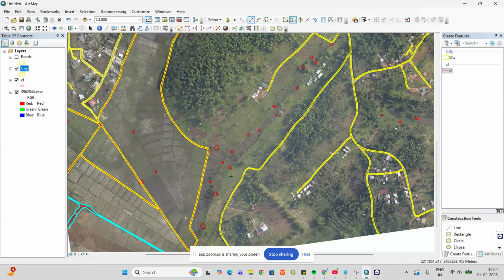But in order to get this 1 square kilometer, if normally we are performing, for example, 5 flights, because at 100 meters we can cover around 50 acres per flight, and 250 acres is equal to 1 square kilometer, approximately, I'm telling you. So normally, if we perform 5 flights to cover 1 square kilometer, now we have to do 15 to 20 flights to cover 1 square kilometer.